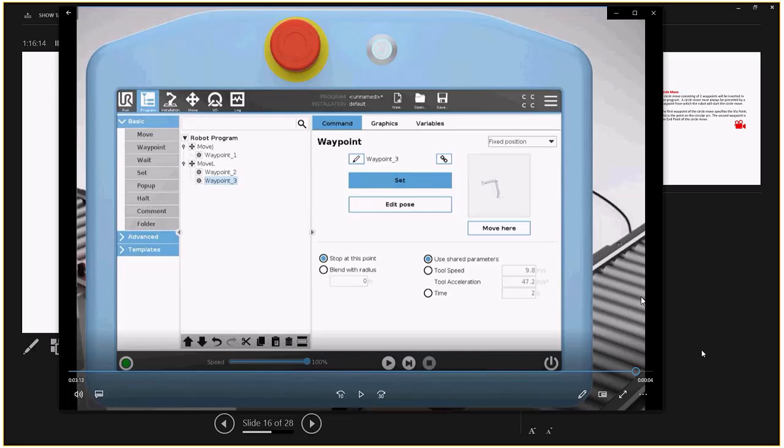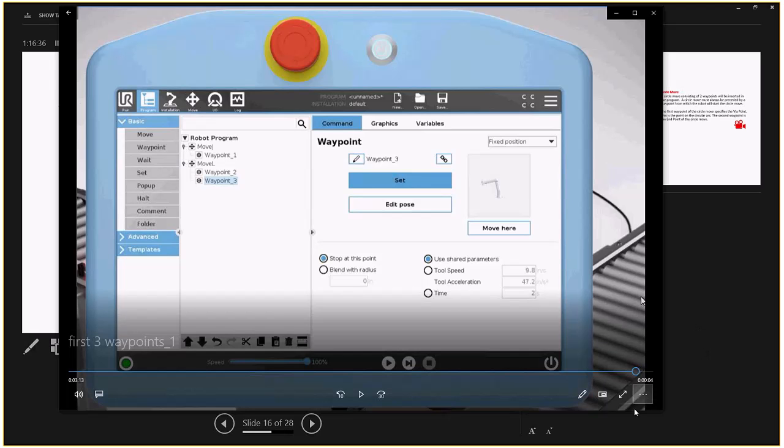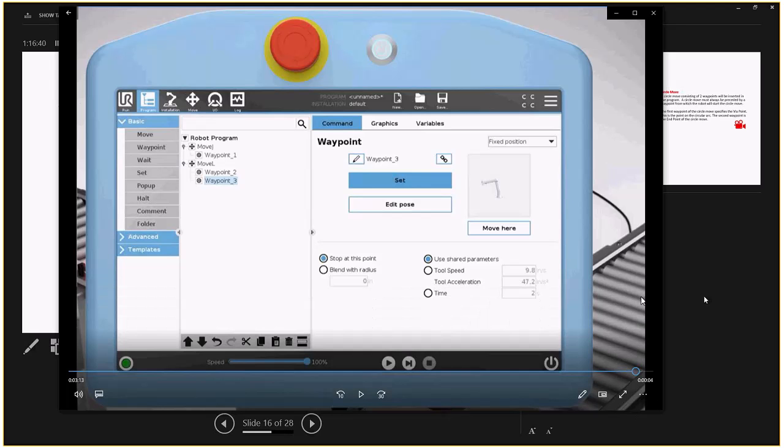It doesn't matter then if you're moving L or P. But if you want to work towards the speed of the robot, for the time that you're processing, sometimes move P will be the best choice, because it doesn't stop in that corner then. And the guys online, any question? No questions. Okay, cool.